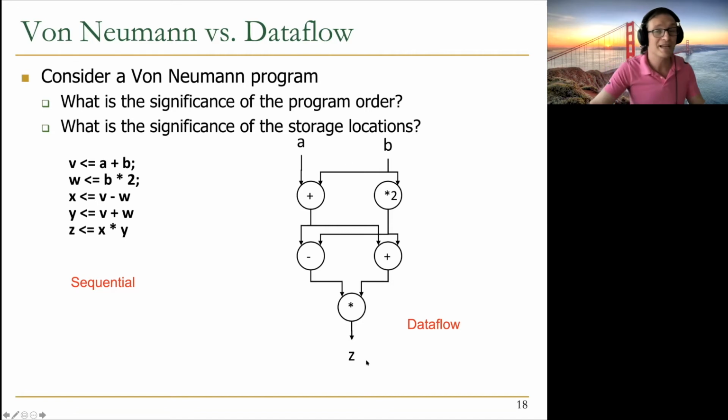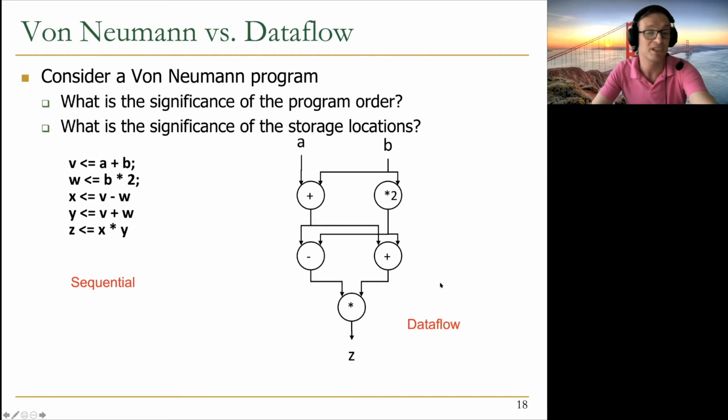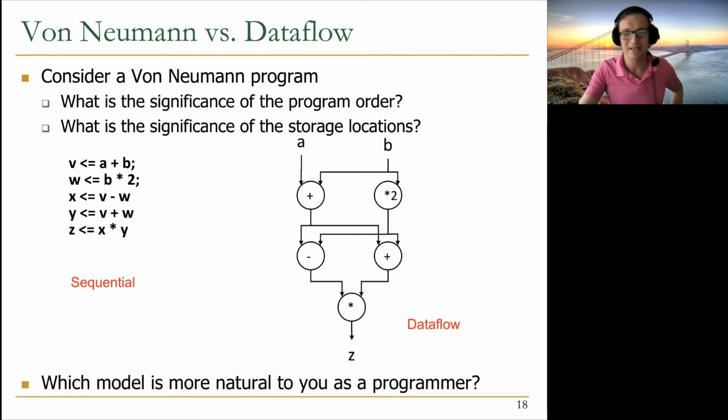That way, you can get rid of the registers, and you just communicate the values through wires, for example. So you could imagine implementing this exact thing directly as logic gates on an FPGA, for example. That's why FPGAs are actually very good potential data flow engines. They don't have an ISA, right? You can directly implement a graphical data flow graph like this on an FPGA by programming the bits on an FPGA as you are doing in your labs. Okay, so this is important to distinguish, basically, and that's what I wanted to mention over here.